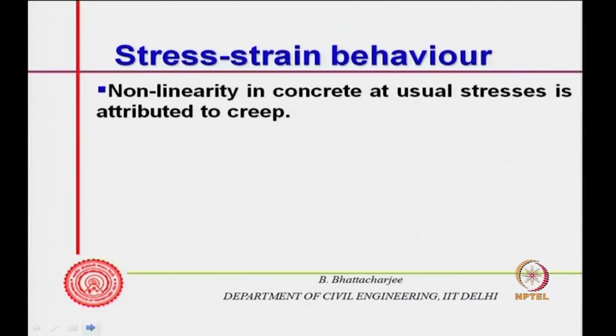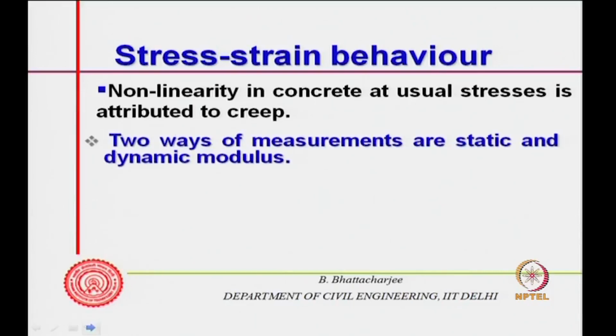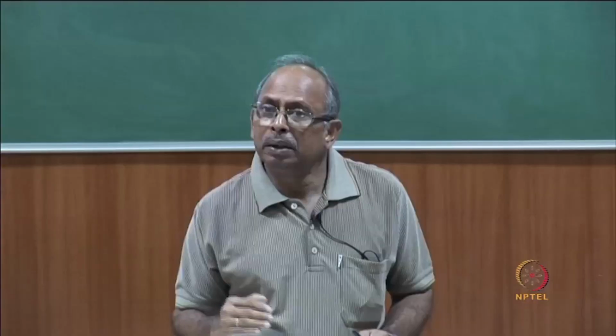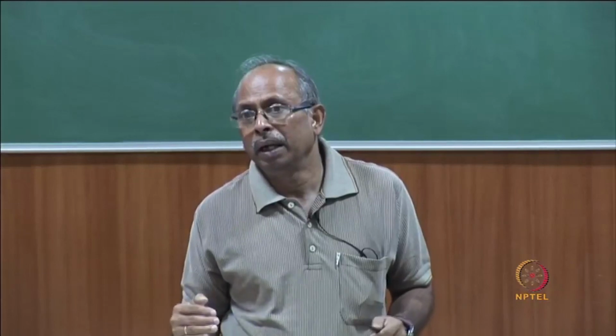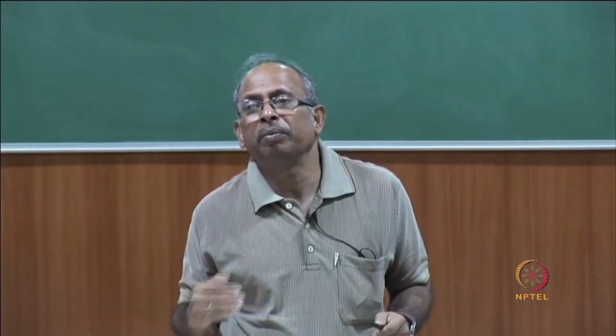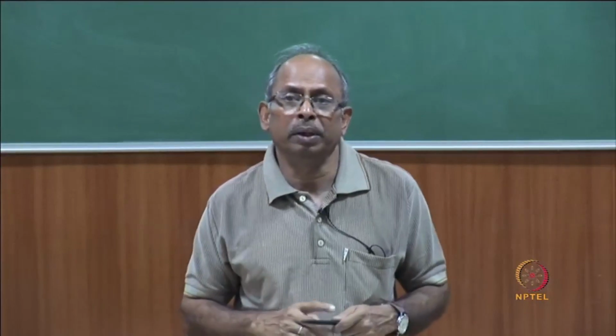Now, if you look at stress strain behavior, it is nonlinear, that is what we have shown, and this is attributed to something called creep, that is the deformation under sustained loading. We will come to that sometime. It is one way of looking at it, but there is something more we will look into. We can measure this under static condition, another is under dynamic condition. Static condition means you apply the load monotonically in steps and measure how the strain changes corresponding to stress, and from the stress strain curve you can find the modulus of elasticity.